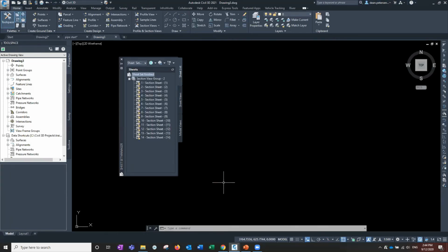So there is a new command they put into Civil 3D here, and it is called enable DST lock. That's a new one in 2021.1. You go enter, and by default it's on 0. It's turned off normally. So if you want to be able to work with these, just go into enable DST lock and type in a value of 1, go enter, and then when you open it, if I come back to